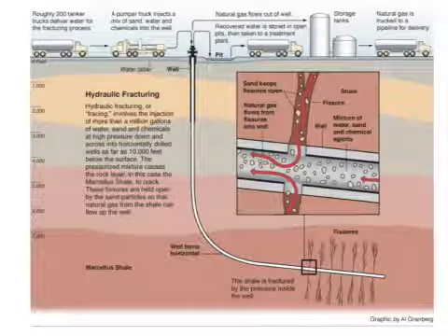The process of fracking starts with a drilling well that passes through the aquifer layer. A steel tube called a surface casing is put inside the well. Cement is then put inside the well and outside the casing. It is then pressure tested to ensure hydrocarbons and other fluids don't seep into water supplies. Next, it is drilled further and more cement and casings are applied as it goes deeper.